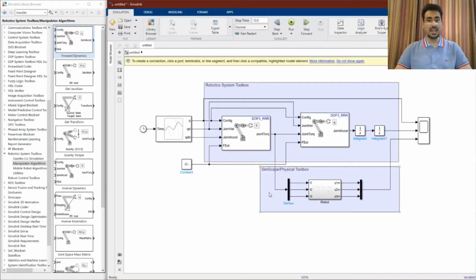We used inverse dynamics of the robot to get the torques required for movement on our desired trajectory. Then we fed those torques to the forward dynamics of the robot that will take in the joint torques and will give us the joint accelerations and ultimately joint positions. These joint positions should ideally be equal to the joint positions corresponding to our required trajectory, and we saw that they were in fact equal.